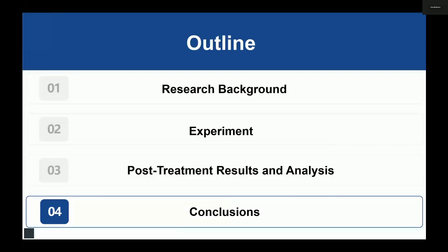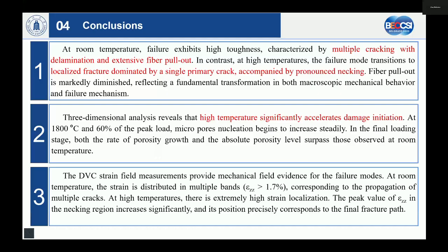Finally, we have reached our conclusion section. The first is that at room temperature, failure is characterized by multiple cracking with delamination and extensive fiber pull-out.